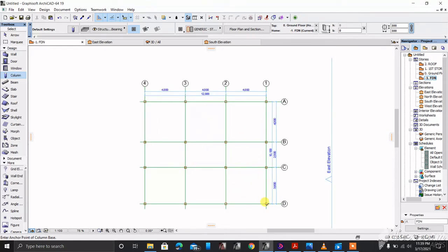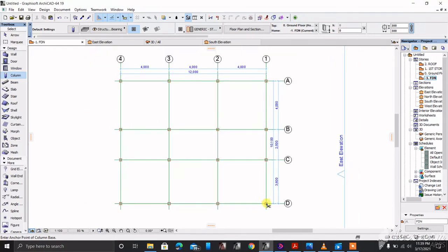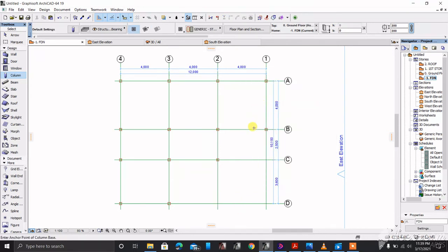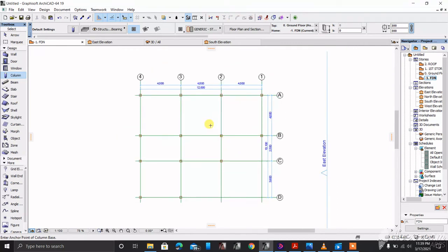Like you can see here, we're not going to need this one, so I'm going to press my shift, then I select. I'm not going to need that grid, then shift, I select this one as well. Because we're not going to use them, after having done that, you left click, then you delete. Next time I'm just going to press delete.